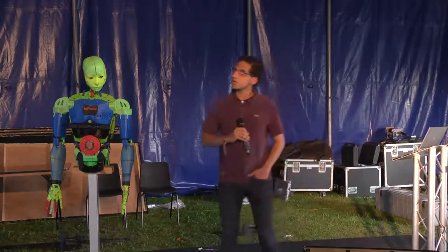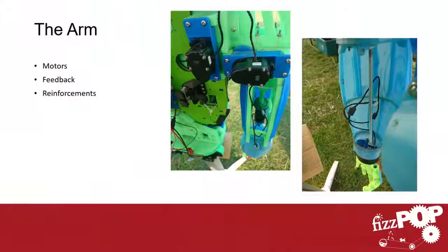So for the forearm, for the whole arm, the original designs were using, again, servo motors. It was using bigger servo motors. And each servo motor will have the wire running all the way to the back of the robot where the Arduino controlling the whole robot sits. Now, the modification I made here is because I did not want to have all these wires running back, because that adds problems as the robot moves its parts.